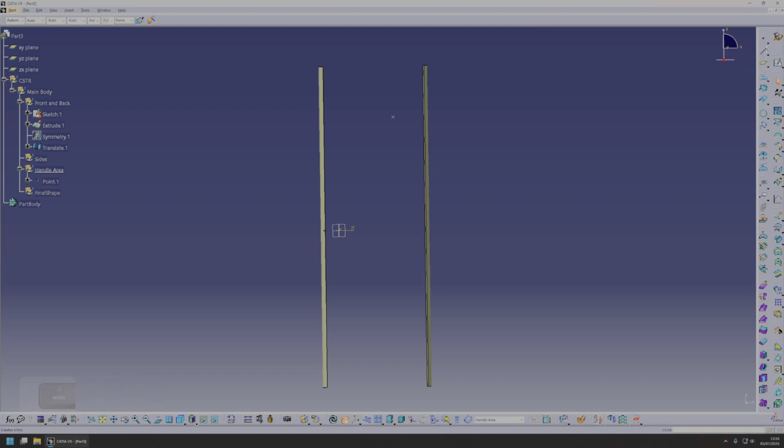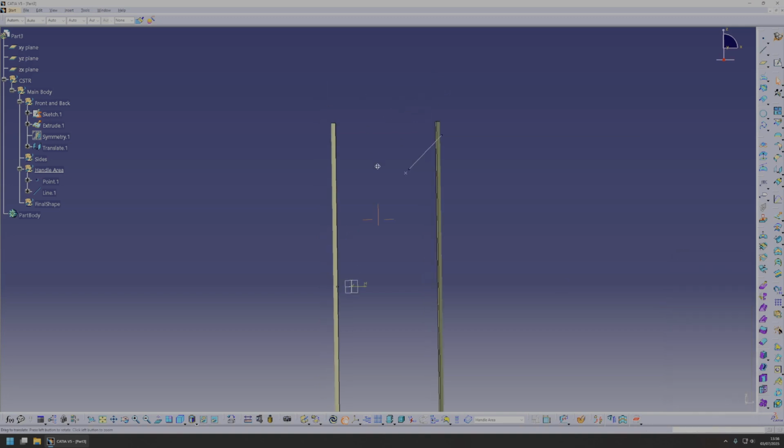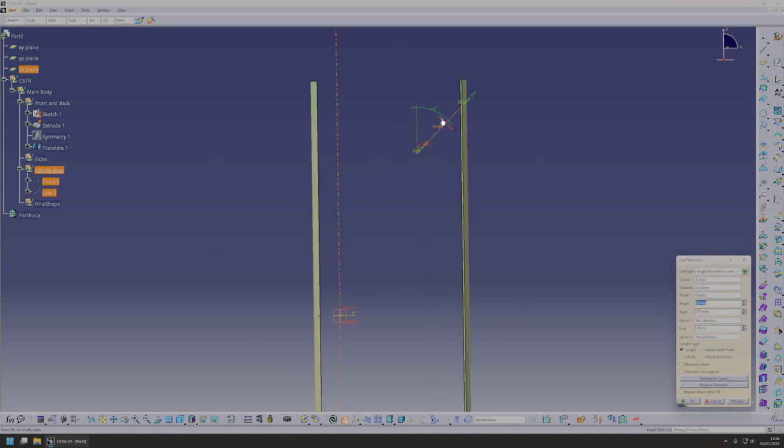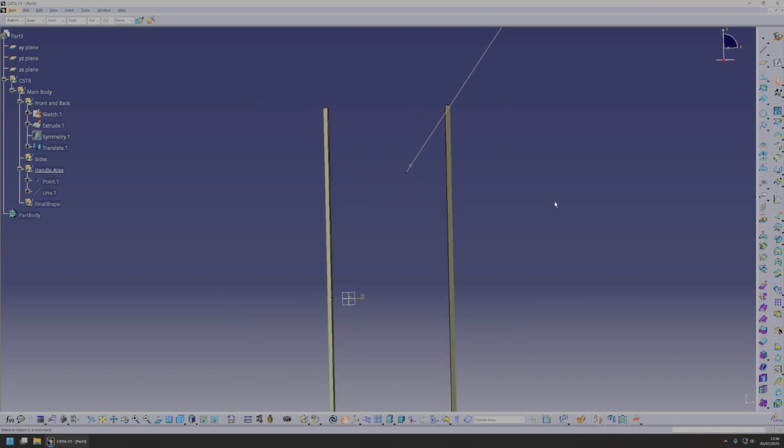We're going to have this point, and we are going to define an axis for this point, and we're going to have angle number curve. First curve will be, I don't know, z-axis. We will have it on this support. Maybe 45 degrees is a little too much. Let's go 35. Yeah, just so we have a general direction for this.